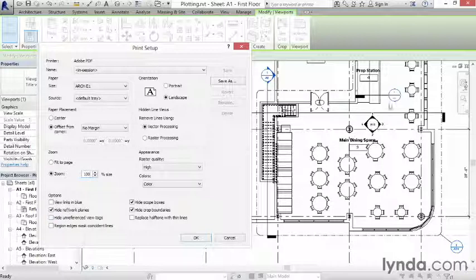Now, the unreferenced view tag is this guy right here. That view tag is not yet on the sheet, so that's considered an unreferenced view tag. Compare that to this section marker here and this callout right here. Those are referenced view tags. So if I check this box, Revit will hide this one when it prints, but these two will continue to display. You don't want to get a phone call from your recipient asking you where this detail is if you didn't include it in the set.